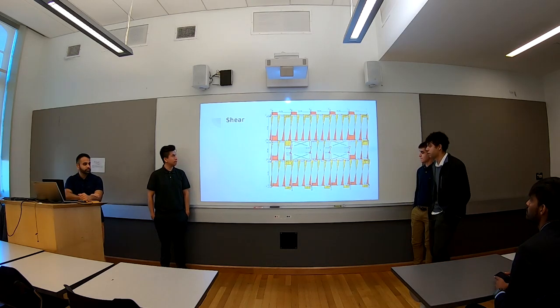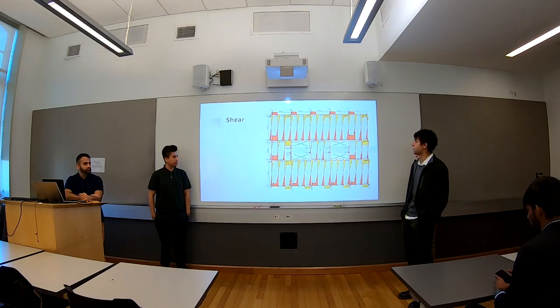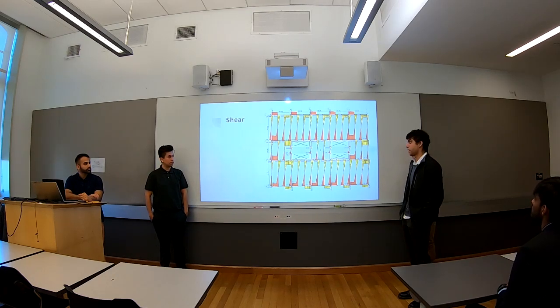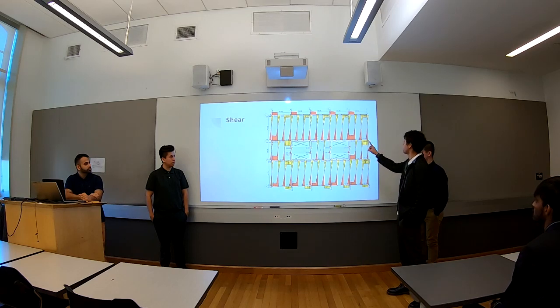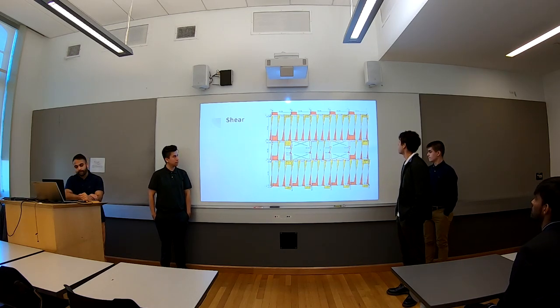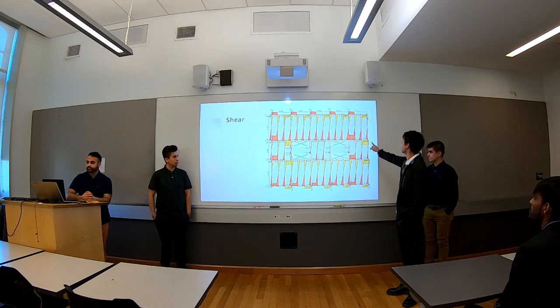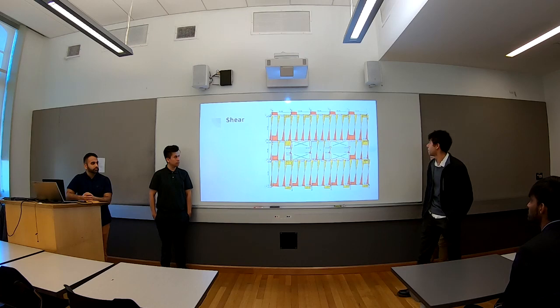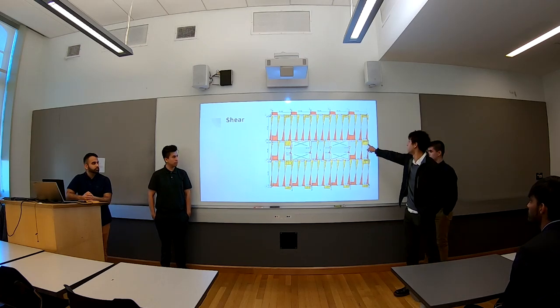Here we have the shear output given from ETABS, and in order to validate this, we did hand calculations. You can see we have 30 by 40 foot bays with 2 intermediate beams in the bays. That gives a tributary width of 10 feet for each intermediate beam.